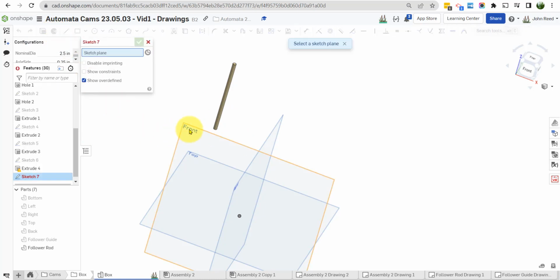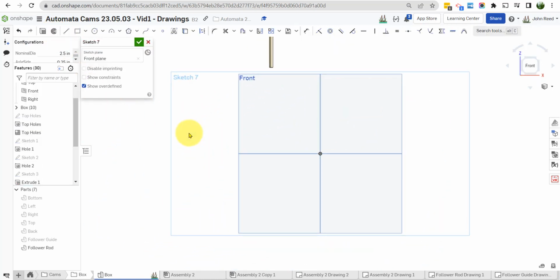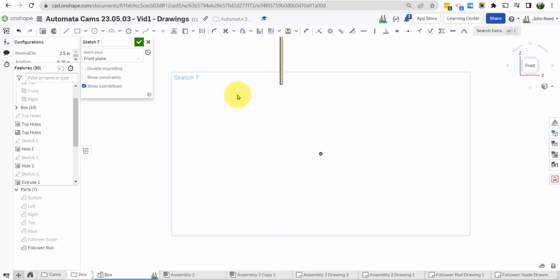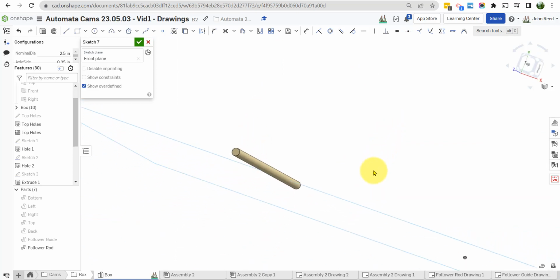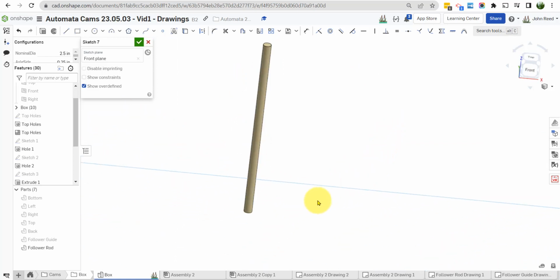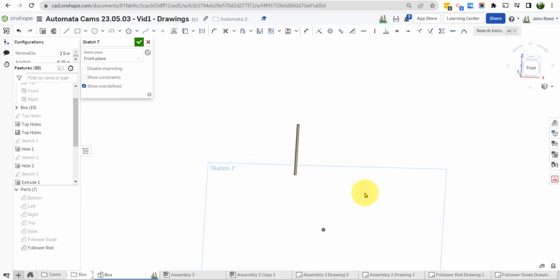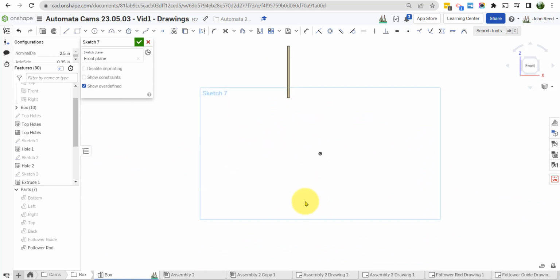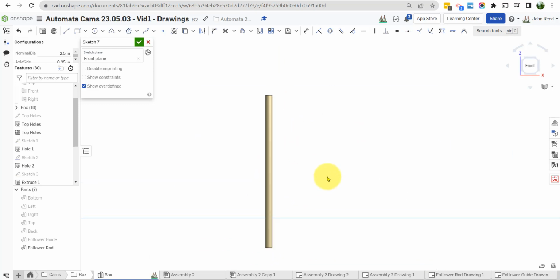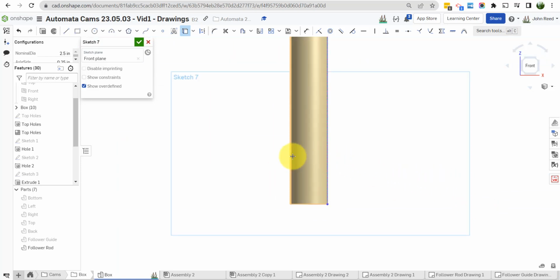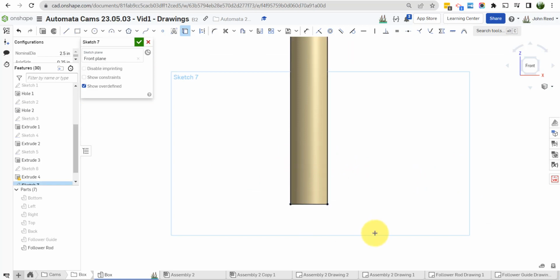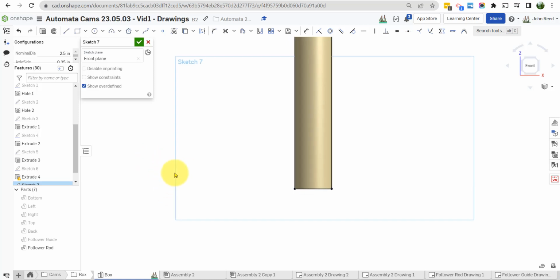So I'm going to place a sketch on the front plane here. Press N. And here's our sketch plane. I don't need the origin planes anymore. Remember, it goes right through there, as you can see right here. Even though it doesn't appear to go all the way up to the rod, the sketch plane is infinite in size. And so what I'm going to do is use the Use tool. I'm going to zoom way up, make it easy for me, and I'm going to use here and here and here. And I am going to use that geometry to make what I want to make.